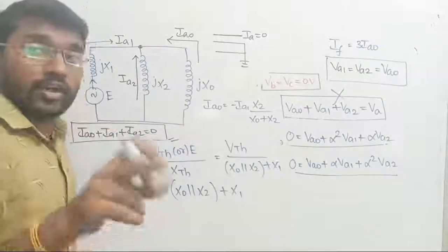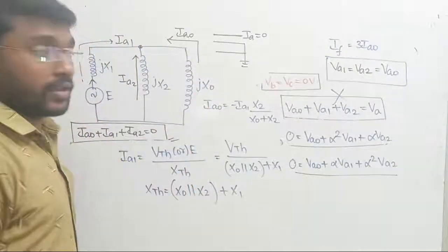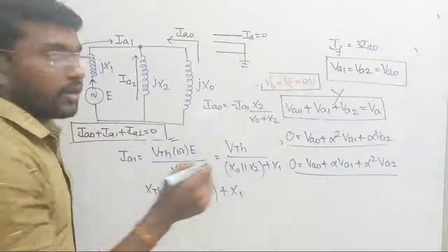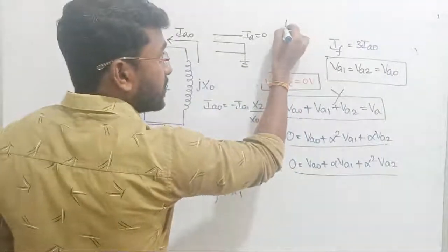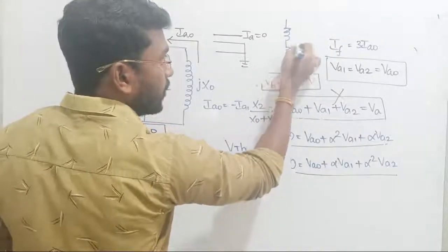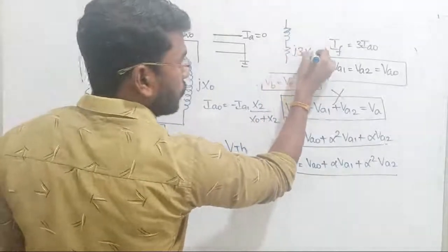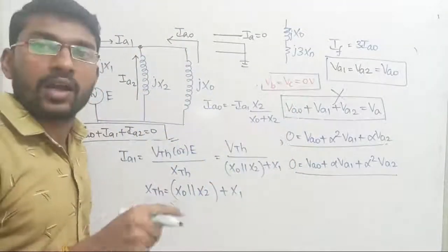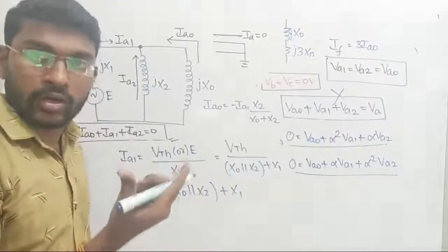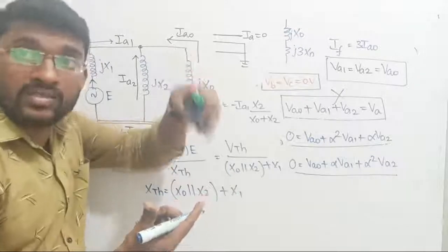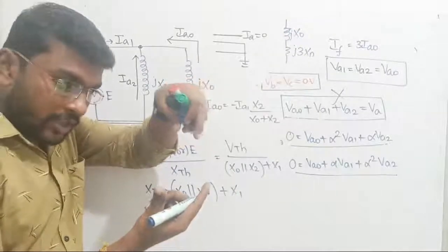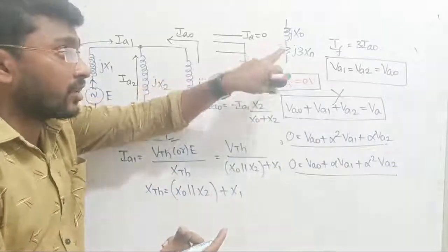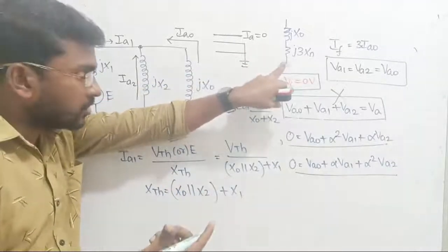Some of you are asking, sir, what do we do if there is a neutral with zero sequence? I mean, what happens when zero sequence is present? I already said, wherever zero sequence exists, that is the point where we consider the effect of neutral reactance also. Yes or no? Where zero sequence has come, who is there? It means neutral grounding is there. Only through grounding will the zero sequence component exist. When we talk about grounding, we are talking about the zero sequence component. So where the zero sequence component is present, a neutral reactance will be there. Fault impedance also will be there.